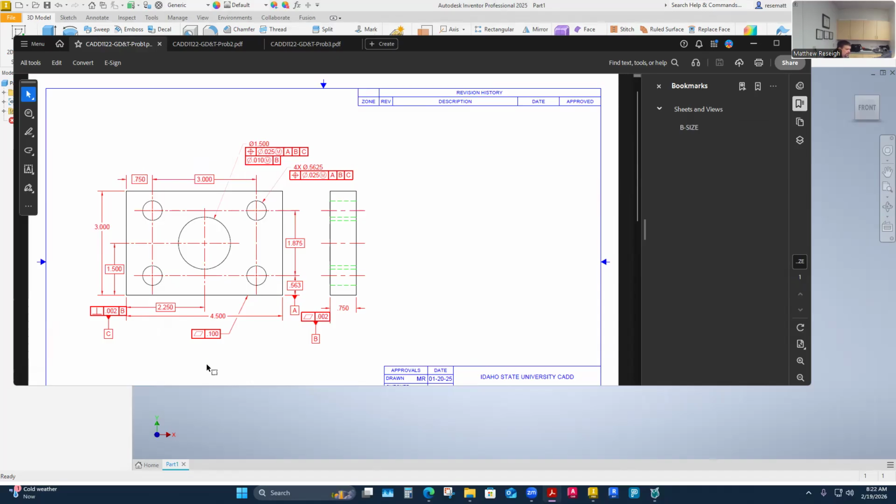What also stood out to me is just some of the drastic difference in tolerances that I have here. Even if I was going to use them, this is a 10th tolerance on a flatness. That might be a little coarse, unless it's a real, I don't know. It seems quite coarse to control that at 10, or 1/10. These seem to be too fine of a hold to me, like 2 thousandths on a flatness and 2 thousandths on perpendicularity. It seems to me that's ultra fine and ultra hard.